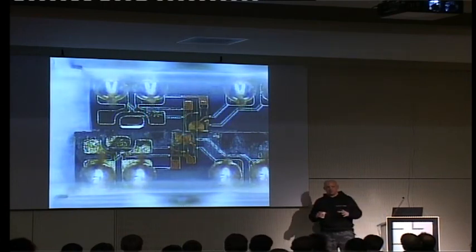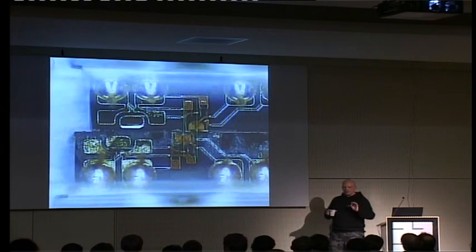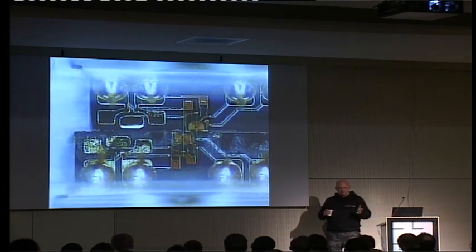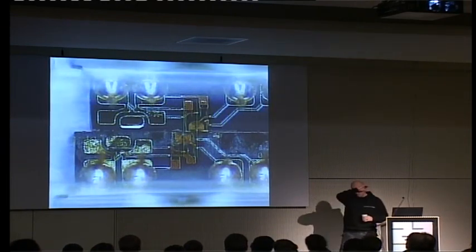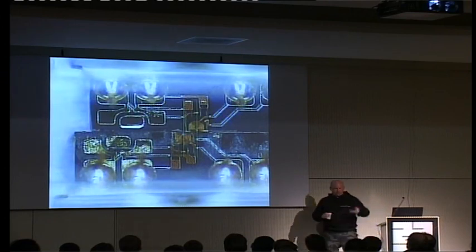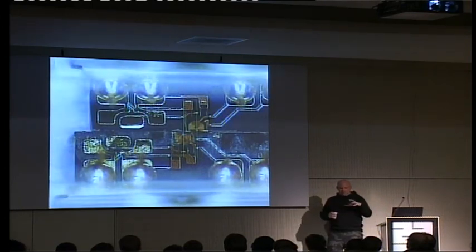There is always only one head selected at a time in a hard drive, meaning when you read, let's say, the top surface and you're going down to the bottom surface of the first platter, then you have to switch heads. And of course, when you switch heads, then you have to find the servo on the new surface again, so that you know where you are.